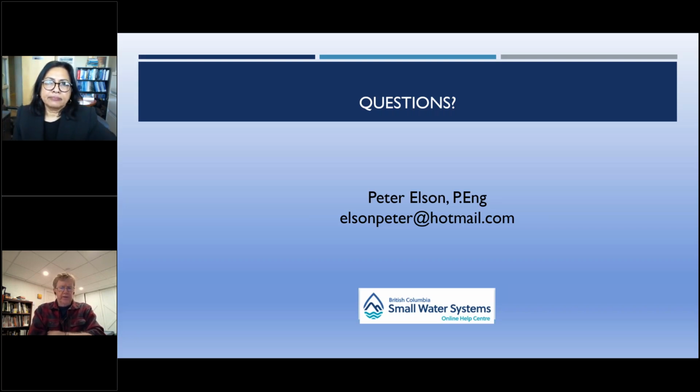But if you're doing it by hand, it's really best that you just make one yourself. You want to look at all the information you need, like the date that you're taking a sample, the time of day you're taking the sample, the actual direct readings off of the equipment you have. And the other thing I would say that they often don't do is make sure underneath, for instance, if you have a column for flow, you write right underneath there: is this liters per second? Is this imperial gallons per minute? So that anybody else who looks at this can also see exactly what's happening with that.